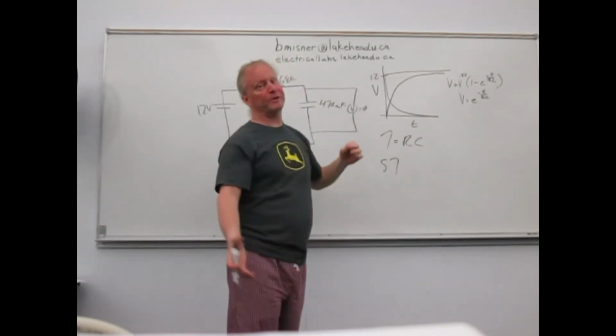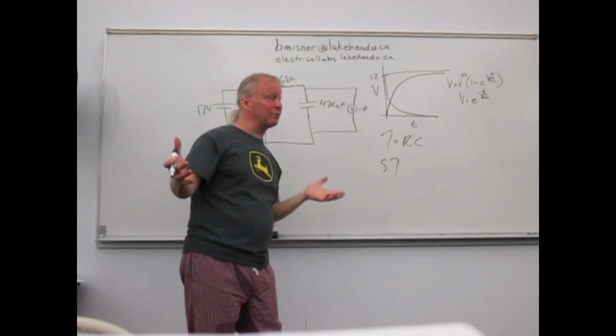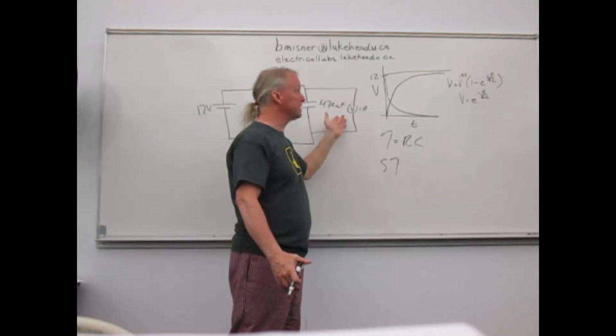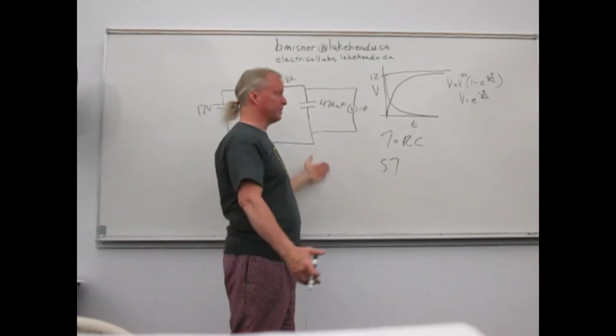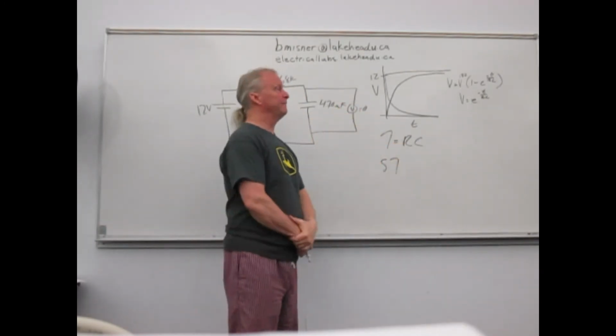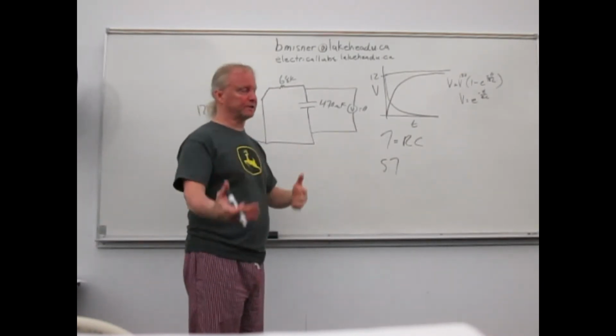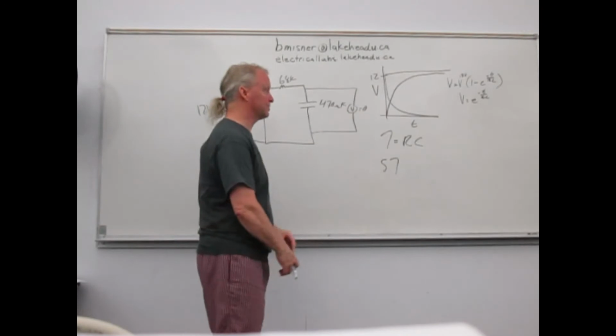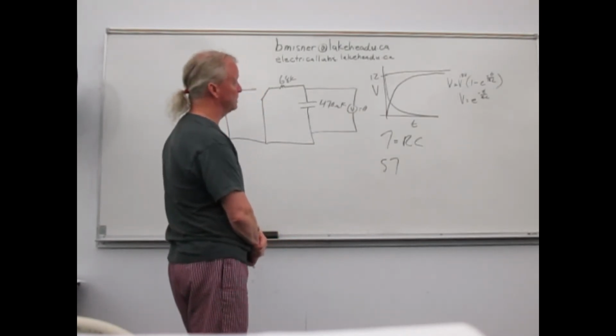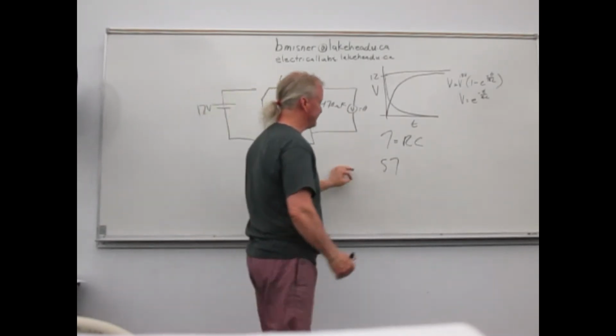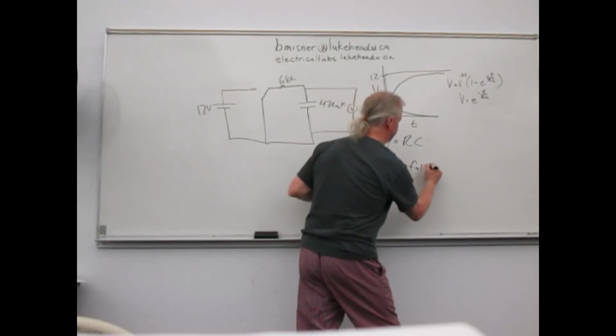When we do our measurements, essentially that's what we're doing. We're going to be charging this for a certain amount of time, and it's going to be another chart that you have to do, and then you'll graph the results for the report. So at 5 tau, it's fully charged.